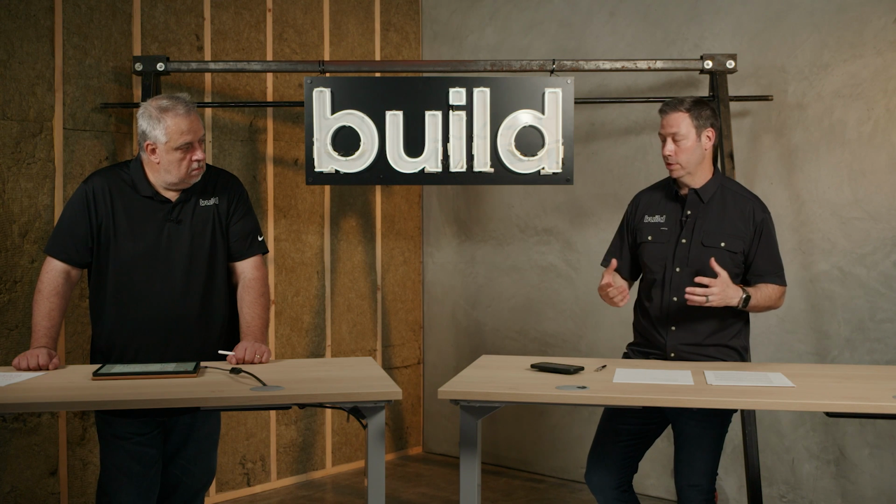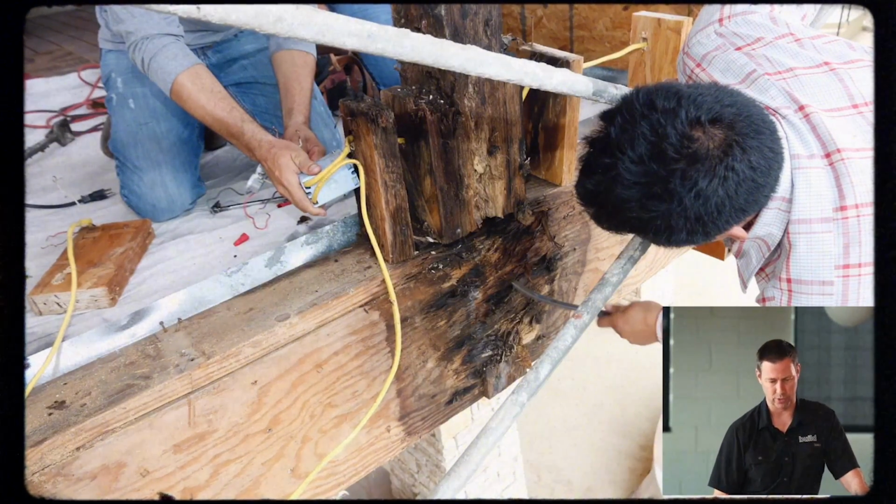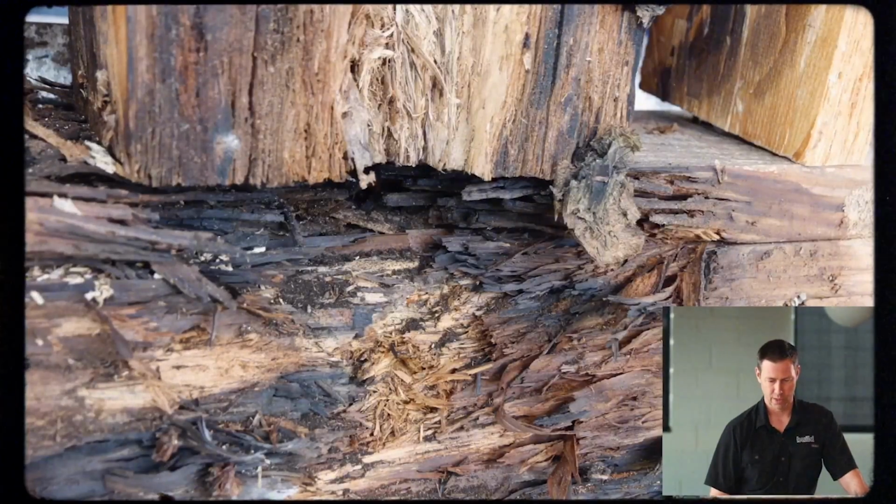Now, on a one-time event, you have a storm that happens once every 10 years and you have some crazy wind and some water gets in, you're probably not gonna have a long-term issue. But if every time it rains, or every other time it rains with a little wind, that water gets in a modern building, there's no good mechanism for drying. We don't have that hairdryer effect on our walls. So that means that step 2, that mitigation that Steve's talking about here, is vital.